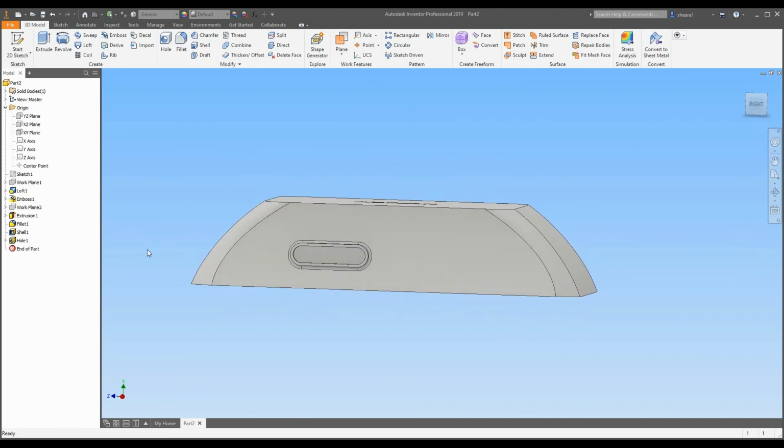Our extrusion is going to be a line through the middle here that will essentially cut our part in half without really cutting that part in half. We're going to use this extrusion, and then we're going to use a tool called push. Basically the push tool will split these two different parts of our object into two different part files that we can use for 3D printing.